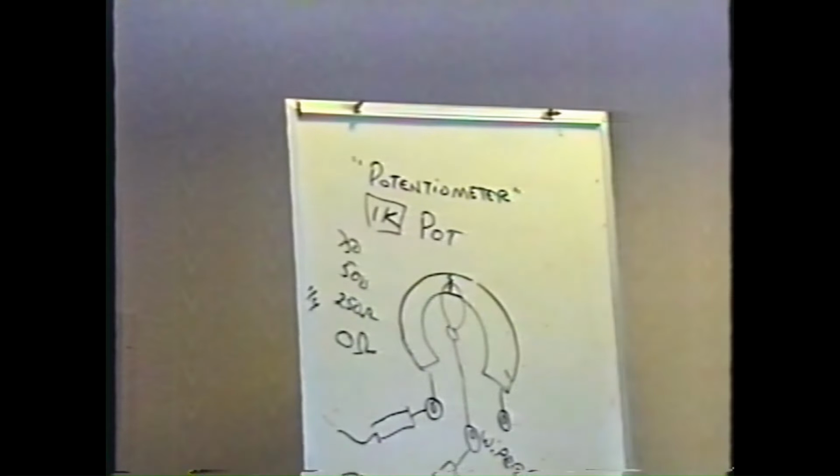Then the other thing that can go wrong with a pot is that the connection between the wiper and the resistance element goes bad. It just gets dirty, basically. And you've probably heard this on your car radio or your stereo at home. You go to adjust the volume, it goes...